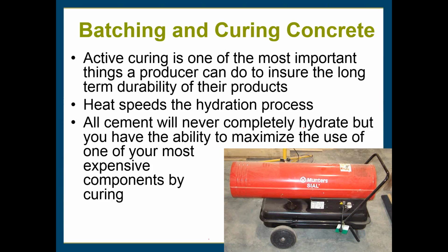In addition, all of the cement will never completely hydrate. But the way you cure can maximize the effectiveness of your cement, one of the most expensive components of your concrete. An example that I always hear Claude use is the Hoover Dam. There's still cement in the Hoover Dam that's still hydrating.